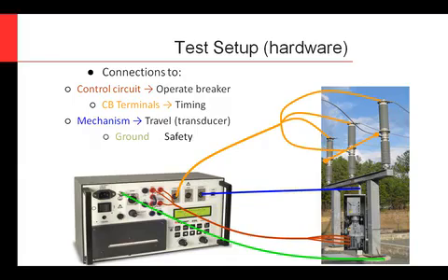No, the pre-insertion resistors, what happens is it'll come in and it'll close, and then the main contacts come in. But after the main contacts come in, even though it's technically shorting out, that resistor will still come back out of contact. So only the main contact is actually engaged when that circuit breaker is closed. And this does add a little bit of complication to the internal designs of that interrupter.